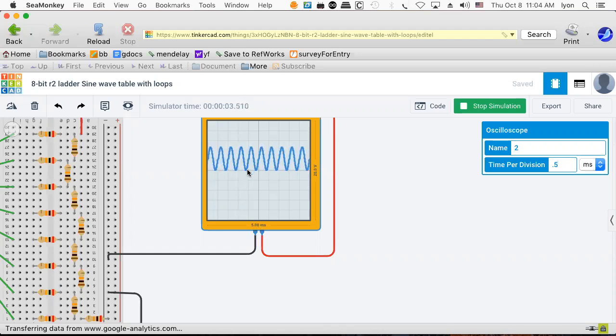I'm not quite sure how this correlates with one versus the other, but if 1 division is equal to 5 milliseconds, then that's 5 1,000ths of a second, and 1,000 divided by 5 should be perhaps 200 hertz. I think the 5 is for the whole grid. The whole grid is 5 milliseconds.